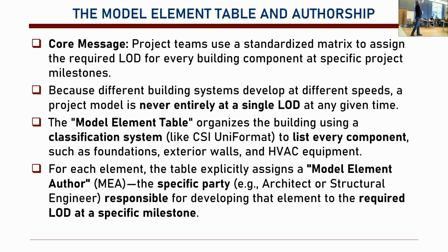So you want to receive different LOD levels for a model element at different stages. Because you have different systems developing at different stages. Architecture can be a bit further in LODs, like your architecture could be LOD 300, but your structure could still be LOD 200, okay? So things, they don't go in the same speed in terms of design.